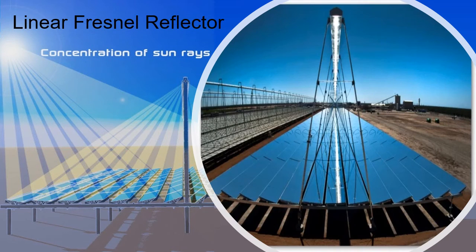A linear Fresnel reflector, or LFR, is another type of solar power collector. It is a simplified parabolic trough which uses flat mirrors as opposed to parabolic mirrors. The basic principle remains the same, the mirrors concentrating solar power onto a receiver tube. An LFR works by utilizing the Fresnel lens effect. This design allows the construction of large aperture and short focal length lenses without the mass and volume of material that would be required by a conventional lens.